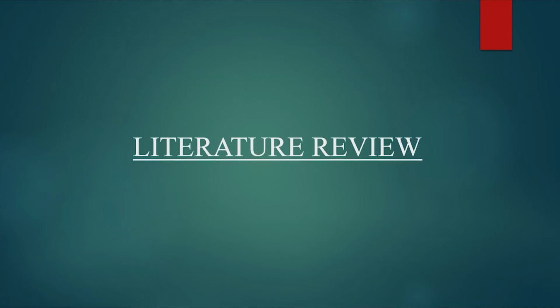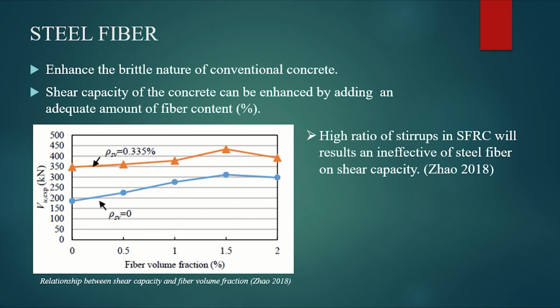So let's move on to the literature review. Steel fiber is a material that can help to enhance the brittle nature of conventional concrete. By adding an adequate amount of steel fiber in terms of fiber content, the shear capacity of the concrete can be enhanced. This figure illustrates that a high ratio of steel fiber in SFRC will result in ineffectiveness of steel fiber on shear capacity. This is according to Chow 2018.